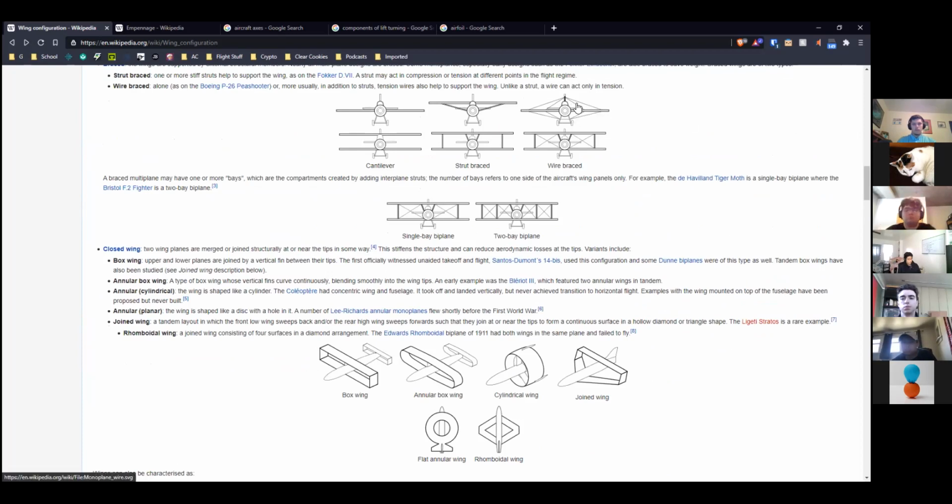And if you have a single balsa stick thickness tail, it's not going to have very much stiffness in the lateral direction. So adding a couple of strings basically, since wires would be unnecessarily heavy, is sometimes a method we use to stabilize it. But the other option is just make it a cantilever by thickening it and using a different profile.